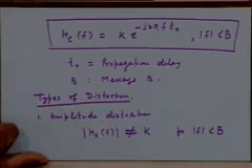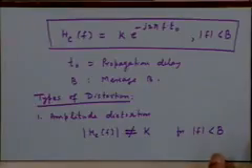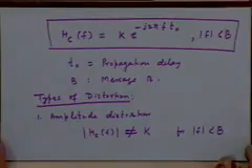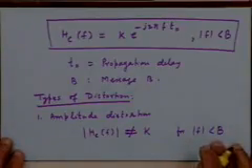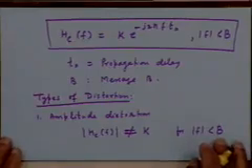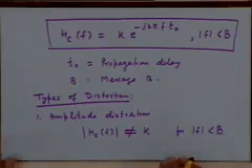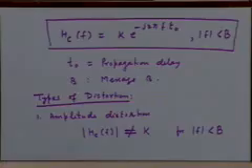If the magnitude characteristic of the channel is not constant, equal to some value k which denotes the attenuation, then we say that the channel is introducing amplitude distortion, in the sense that the different frequency components present in the message waveform m(t) are being amplified or attenuated differently by the channel.